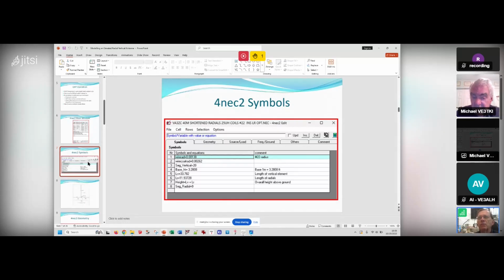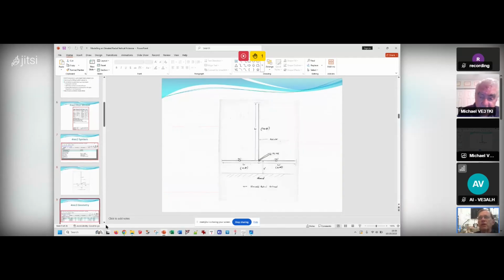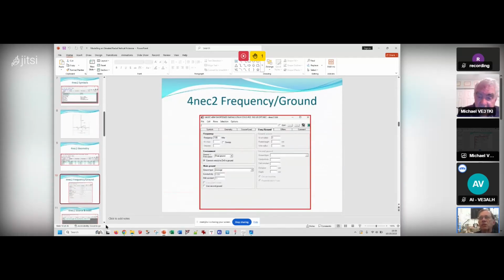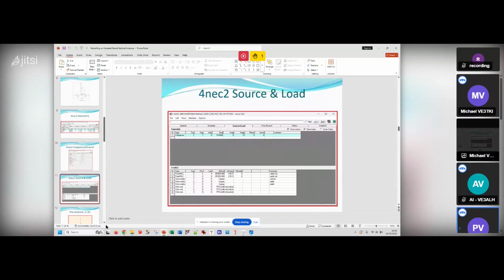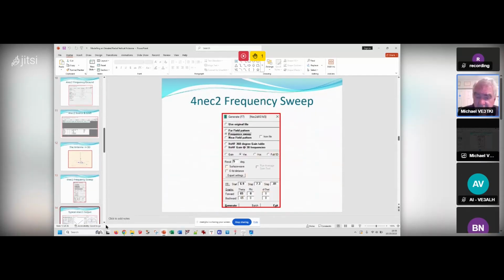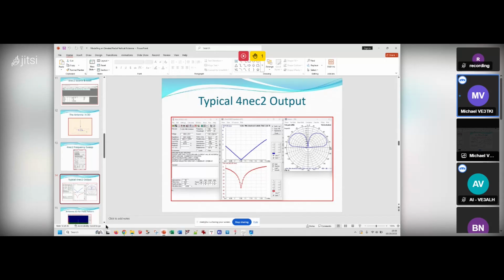Like when you did your last measurements and ran NEC2, it spat out the impedance and the SWR. And then I assume you ran the VNA with that setup outside in the real world. What were those comparisons like? Well, the model came up with 7.05 as the resonant frequency because I'd asked it to do that, and I had optimized the lengths. So what I actually built was what the program told me to build.